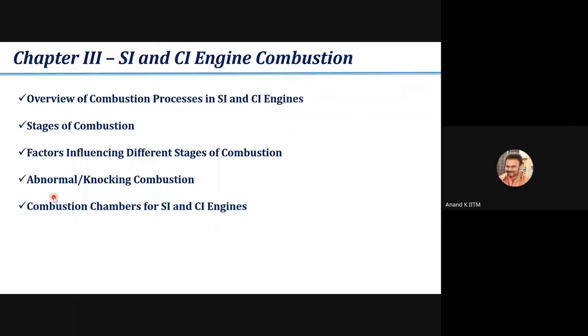One is improving the power output from the engine. Thermal efficiency should be higher, and combustion should be smoother without any abnormal combustion or knock. All these depend on how we design the combustion chamber in terms of fixing the locations of intake and exhaust valve, spark plug, and also fixing the shape of the piston and cylinder head. So we have discussed how we can improve power output, thermal efficiency, and how we can have smoother combustion based on the combustion chamber design.